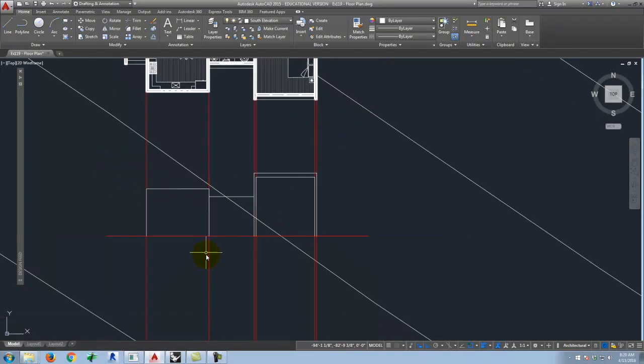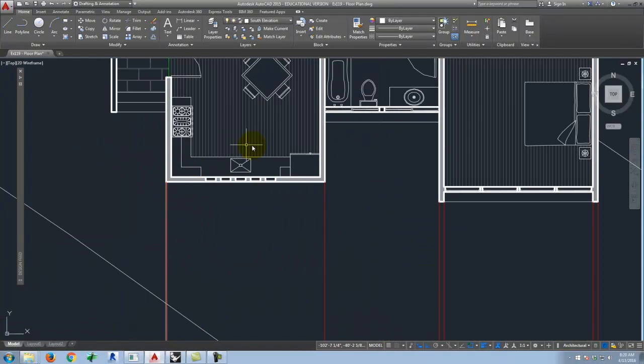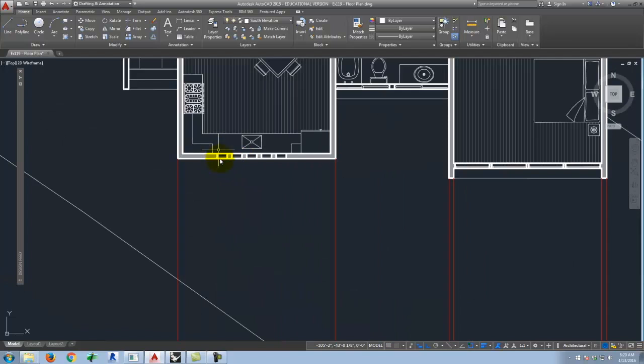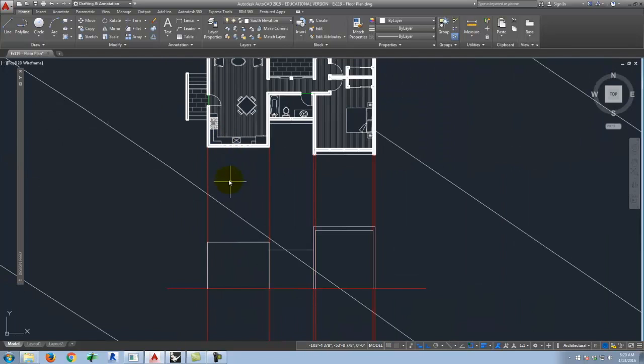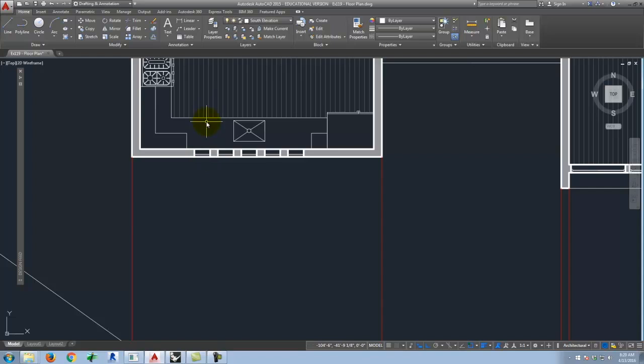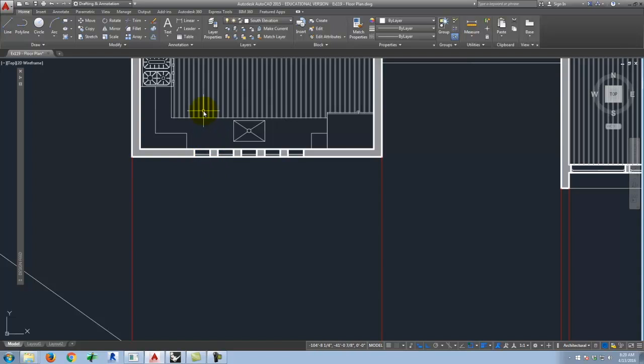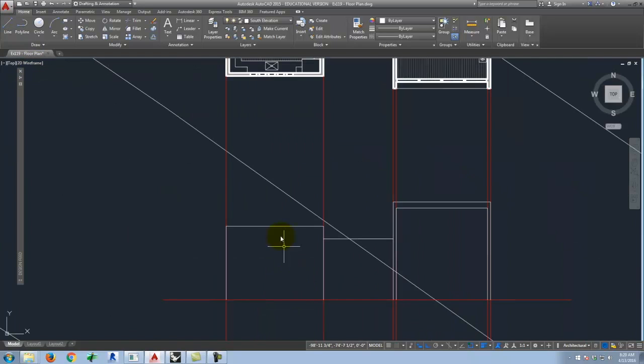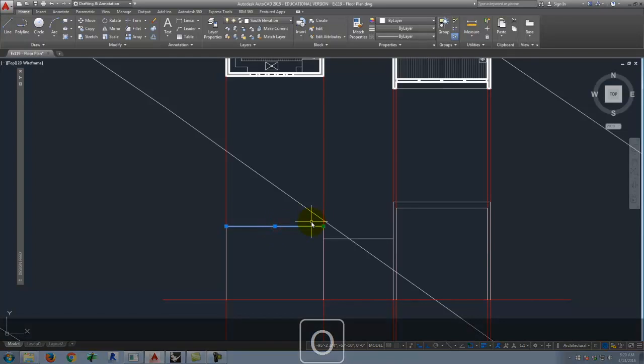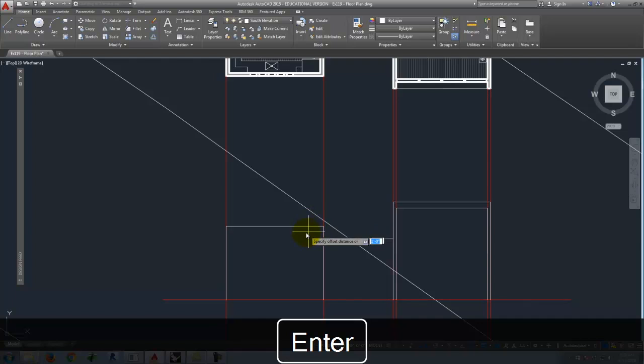I want to do the same thing with this wall, except this wall comes all the way up to the roof except for these little windows that are on the wall. So if these windows were above a kind of a kitchen counter, we know that the kitchen counter is 3 feet off the ground, so 36 inches. So these ones probably start at maybe 42 inches. And again, they probably stop at about a foot down from the ceiling or so. So let me go ahead and offset this. And maybe I'll carry them all the way to the ceiling. We'll go 12 inches for the structure.